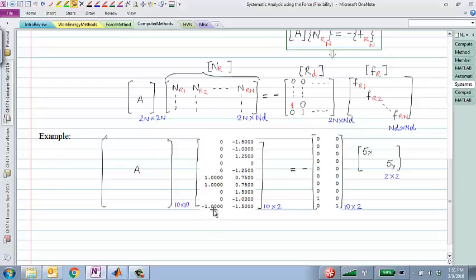Of course, it should, since I'm solving it against an A matrix that we had constructed for the determinate truss. Similarly, if I apply a 5y unit load, I get the solution vector, which is internal forces in the members and the reactions at all the three locations. So solving for this matrix, which I'm calling NR, these are the internal member forces for the redundant systems.